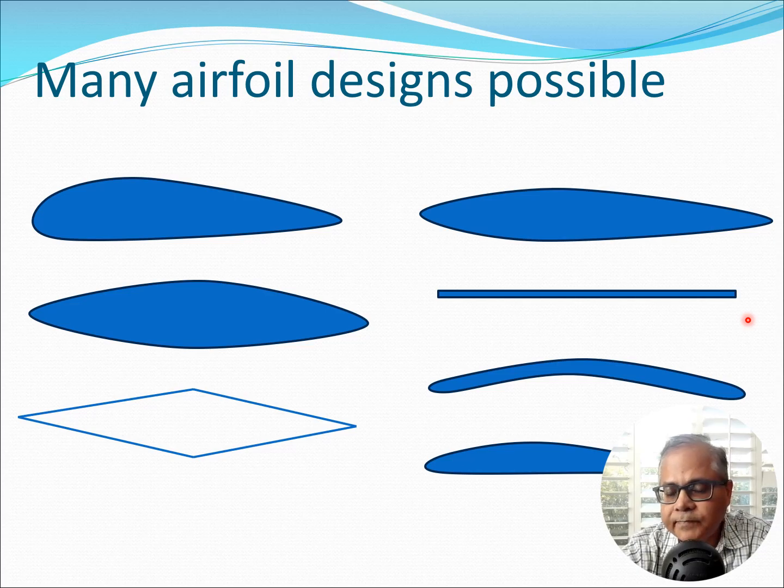And for very small aircraft, we could also have different types of sections. What we are most familiar with, the typical airfoil sections we see, are for high Reynolds number situations of about 1 million or so, where most of the aeroplanes fly. If you are in different flight regimes, the airfoil section is going to be different.